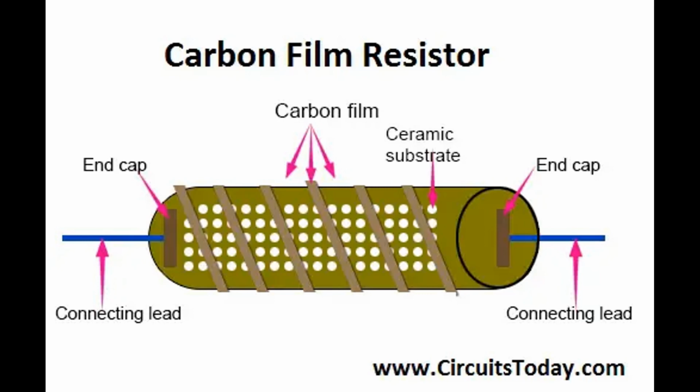In summary, noise in resistors is an unwanted electrical phenomenon that arises due to the thermal motion of charge carriers. It can affect the accuracy and performance of electronic circuits, especially in high-precision applications. Engineers and designers must consider noise characteristics when selecting resistors and employ appropriate techniques to minimize or manage noise when necessary. In the context of resistors and electronic components, stability refers to the ability of a component to maintain its specified electrical characteristics, such as resistance value and other performance parameters, over time and under various operating conditions.